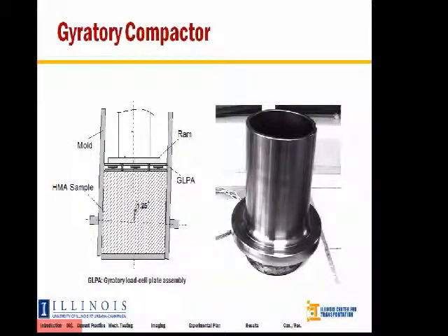Again, just to familiarize everybody, just showing you guys the typical gyratory mold on the right-hand side of the screen, and on the left, just an illustration showing us our angle of gyration. Okay. Our HMA is placed in there. We generally put a top plate on if it is not incorporated as part of the gyratory compactor, and compact our specimen to 160 gyrations during mix design, so that we can look at that N initial, the N design, and an N maximum, the 3 critical gyrations that I showed on the previous table.